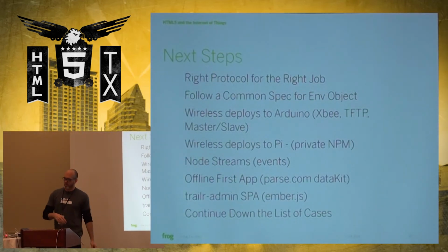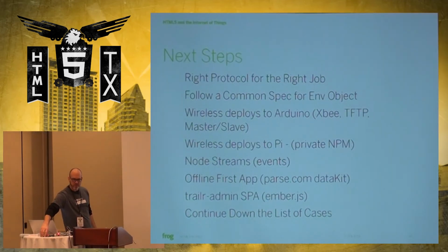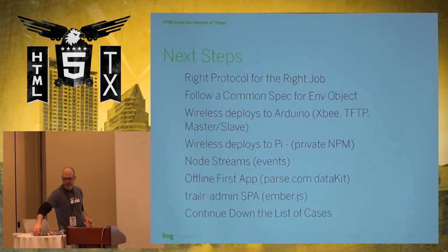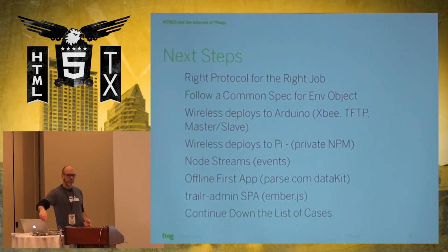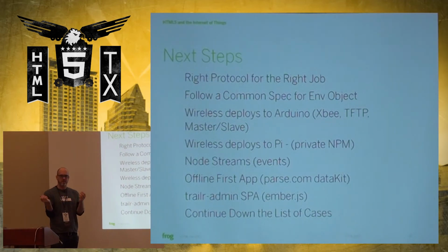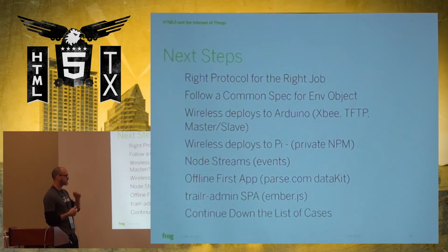Basically, you have a wireless module running on the Raspberry Pi, which in the system I showed you would be the Raspberry Pi. Then the Arduino has a wireless shield, you put the other XBee module on the wireless shield, and you can push across the serial connection.